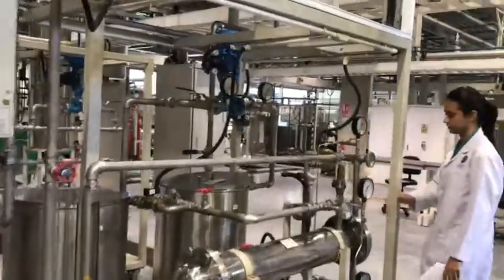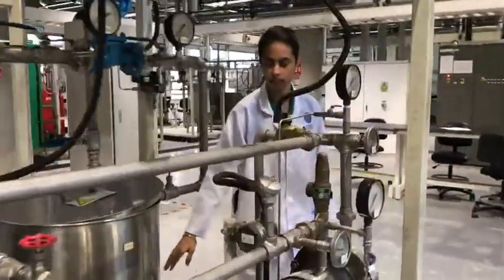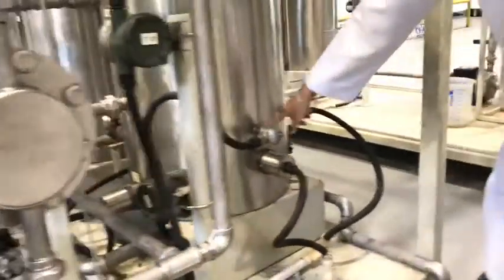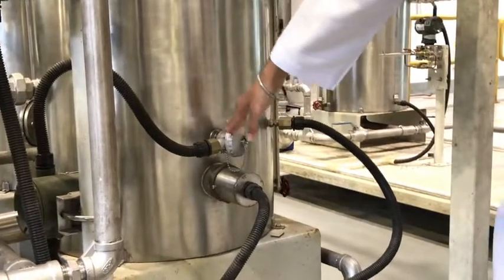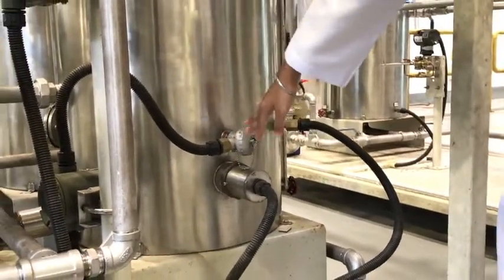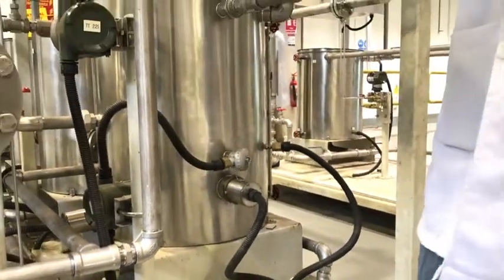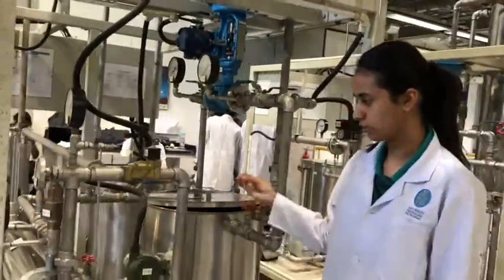And at the first side, there is a thermocouple and a transmitter that will actually send the readings of the controller of the temperature to the control system, and through that we can manipulate the temperature of the hot water and we can know what the temperature is.